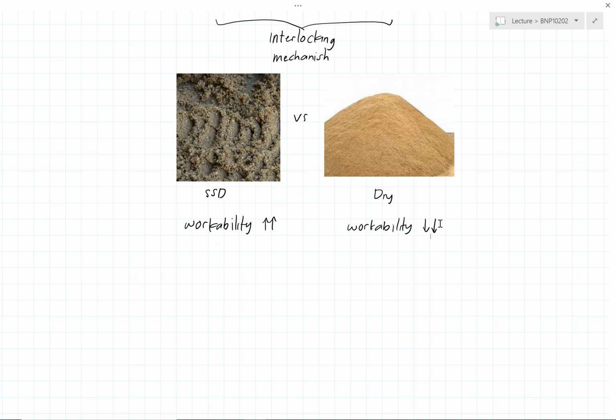What about the strength? It's quite hard to judge the strength performance of these two materials because the strength is also related to the amount of water and the cement content. But theoretically, SSD will give you better strength performance than dry or wet aggregate.